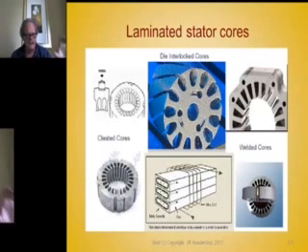It's like a big clamp over the OD in several places. That's not used much anymore. But here's some examples of welded cores. This is a very poor welded core that has filler metal added. It takes up way too much space. It's going to cause eddy currents in there. It's a poor weld. Here's a very excellent weld. Very tiny, small welds. That's desirable.